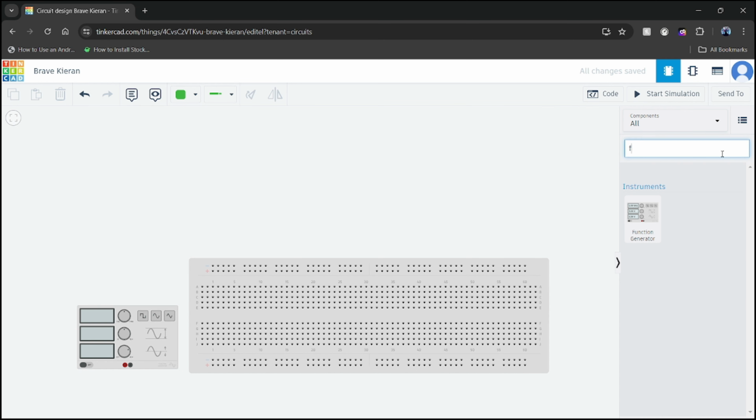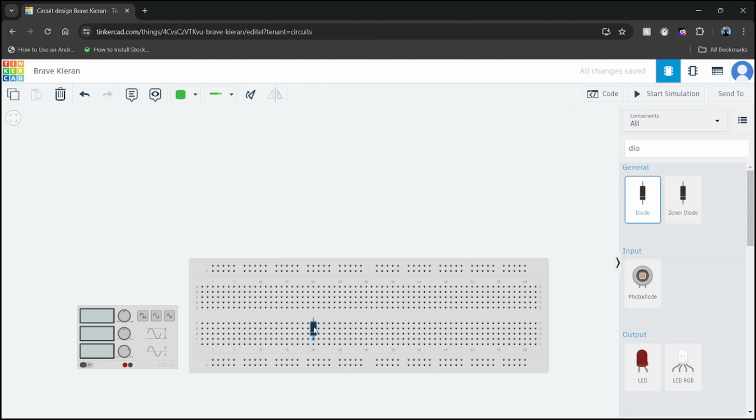And also then start building the bridge circuit, which is made using 4 diodes. For our project, we have used a bridge rectifier where the peak output voltage will be equal to the peak input voltage after subtracting the knee voltage of a diode.